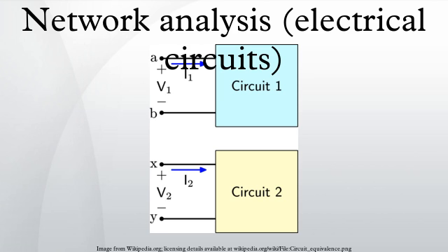Two-terminal component transfer functions. For two-terminal components, the transfer function, or more generally for nonlinear elements, the constitutive equation, is the relationship between the current input to the device and the resulting voltage across it. The transfer function, Z(s), will thus have units of impedance, ohms.